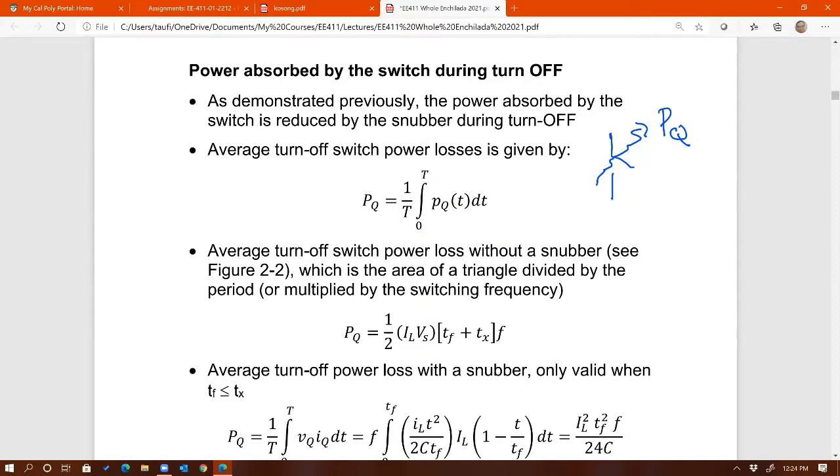And then if this switching loss is too big, that's why we introduce a snubber. In our case, a turn-off snubber, right there. So after you add the snubber circuit, you have two losses, right? Number one, the switch loss is still there. It's not going to go away. And then you also have the snubber loss, like that, right? Now, why do we bother adding this snubber if it adds more loss?